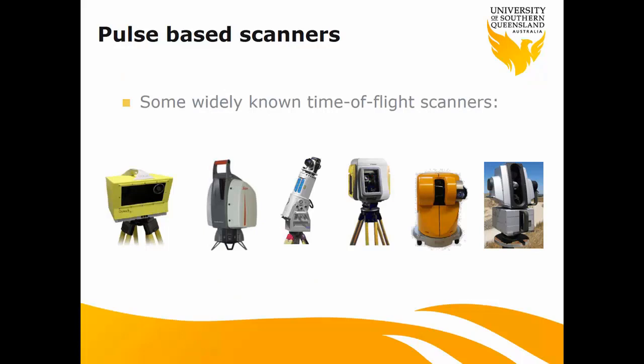You will see this one has no interface for operation. You have to use a laptop, with a cable or wireless connection to this laser scanner. So all your operation is from the laptop. There are two windows. This one we call the major laser beam window, which has a limited area. If you want to scan the top, you have to use the second scanning window. Complicated. This one is Riegl.